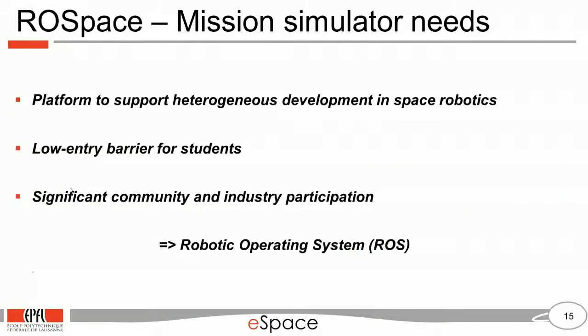If you're coming from a robotics background, then very quickly you will think of ROS, which is the Robot Operating System. It is very interesting to us because it's a middleware, and it's based on two main concepts, which are topics and nodes. A node is just something that allows you to encapsulate your algorithm, your actuator, your sensor. In robotics, for instance, they use a node to control a robot like the KUKA or any other industrial robot.